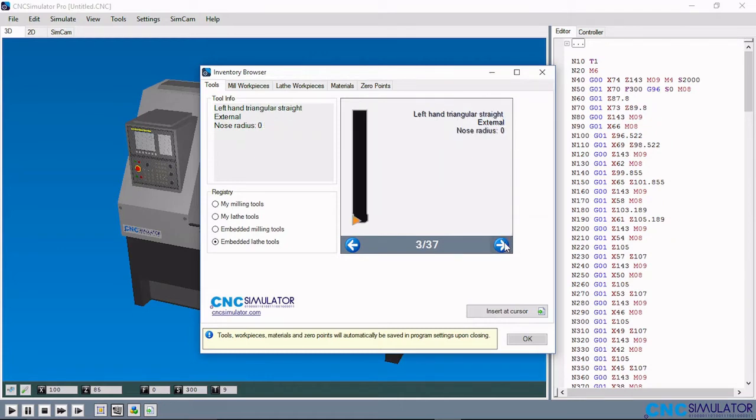Because a CNC machine can take a lot of tools, that is why the tool change is one of the part codes on the CNC machine. So you can always switch from one tool to the other depending on the requirements as the profile to be done on the workpiece demands. Also you can do that for the mill. There are 68 tools in the mill tool registry. Here again you have the diameter, the tool length, and also the tool name, which is an end mill, millimeters. You can always look at all the tools that you have by just clicking and checking all of those.